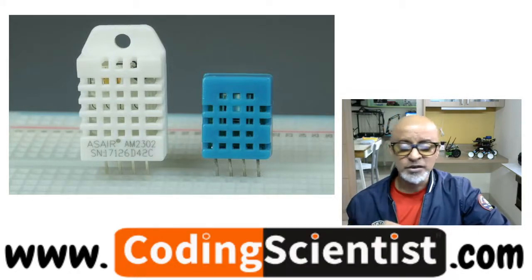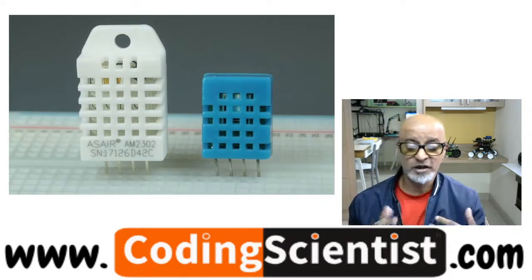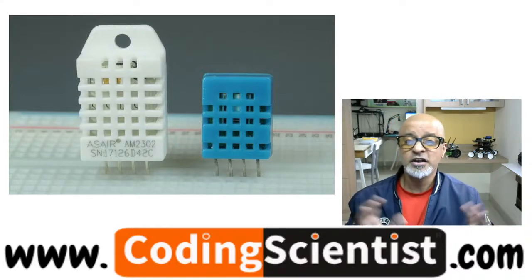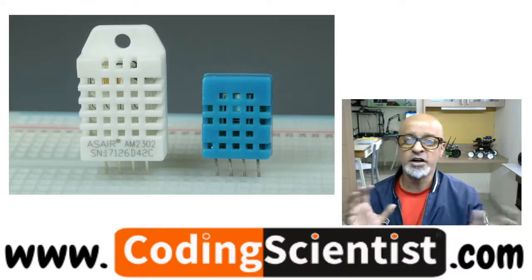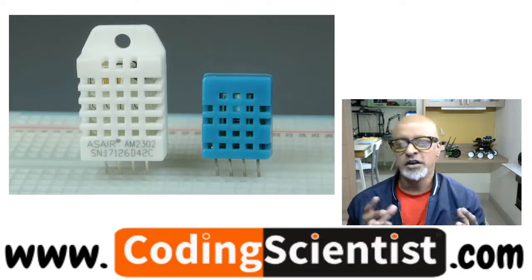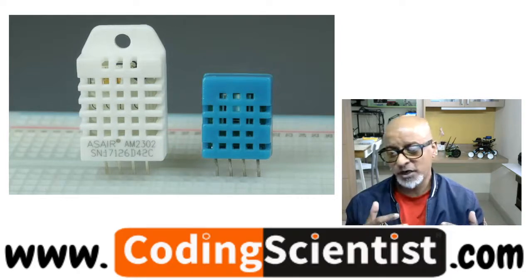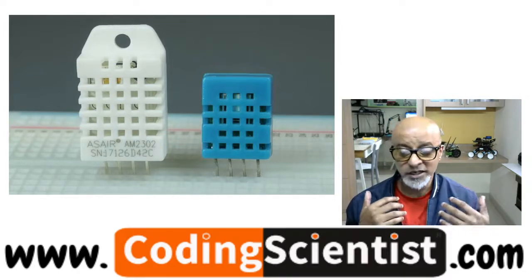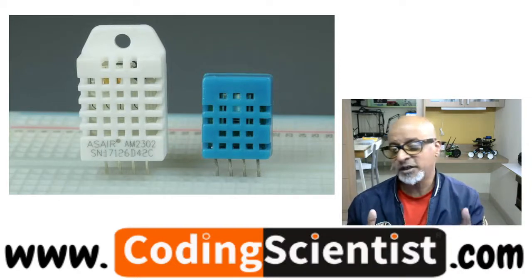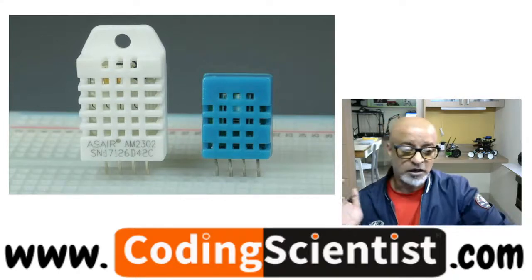The DHT22 sensor has a better resolution compared to the DHT11 and a wider temperature and humidity measurement range. That means it detects a wider, larger environment compared to the DHT11. It is slightly more expensive, not by much, a couple of hundred rupees. You can only request readings at a 2 second interval. Randomly it gets refreshed within 2 seconds. That's a fantastic part, right?